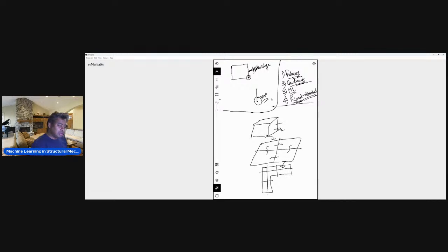even your grain boundaries, for example, in certain hotspots, you will have to have a very informed law, for example, a crystal plasticity law. So in this particular regime, you might want to have a very highly informed nonlinear crystal plasticity law. But maybe these regions over here can have a continuum plasticity law, and then these regions which are further away can have fully elastic regimes.